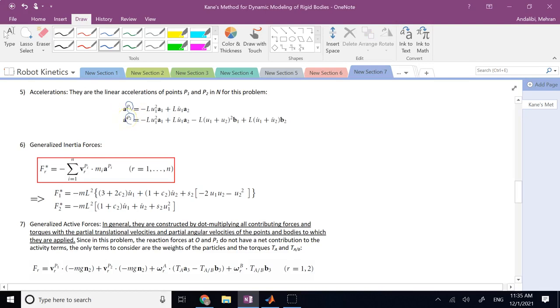All I need to find is the linear accelerations, AP1 and AP2. I do not need an alpha, because alpha is important when you have the inertia matrix I to multiply by that, and it gives you a torque, right? But in this system, these blocks do not have inertia because the rigid bodies have no masses. All the mass is concentrated at the particle. So the rigid bodies themselves are massless, so they don't have I, so I do not need alpha. Just keep that in mind.